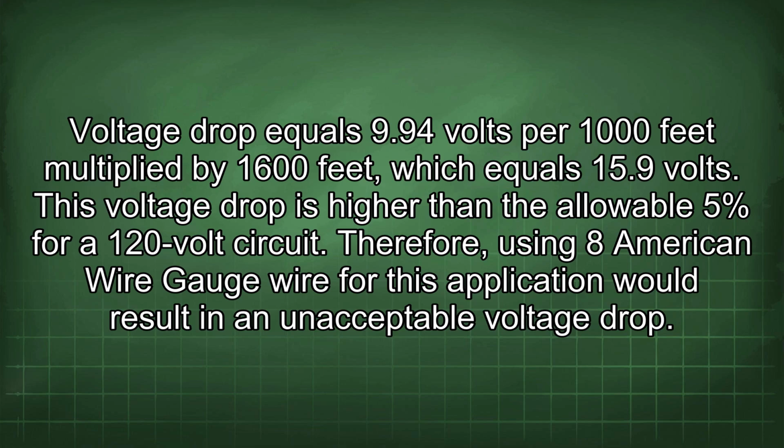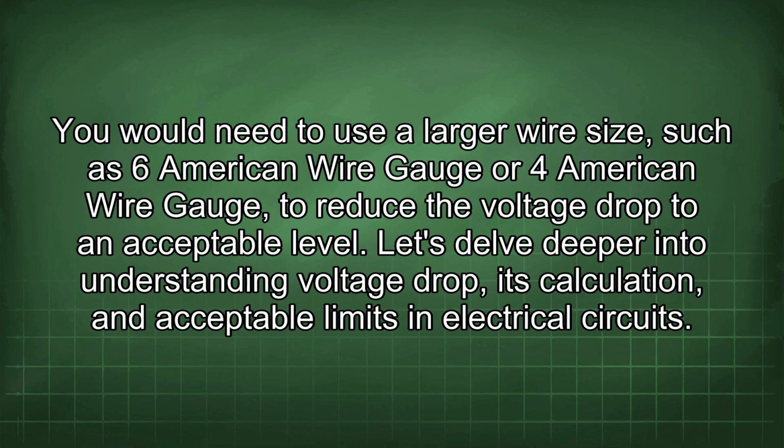Therefore, using 8 American wire gauge wire for this application would result in an unacceptable voltage drop. You would need to use a larger wire size, such as 6 American wire gauge or 4 American wire gauge, to reduce the voltage drop to an acceptable level.